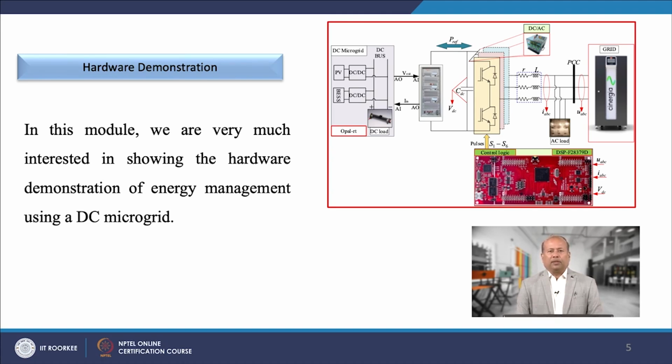Make sure that the ADC pin configured inside Simulink is the same as the pin the signal needs to connect to. The control system processes the signals and generates modulation signals, which are used to generate PWM signals. These PWM pins need to be configured to take out from the DSP board.